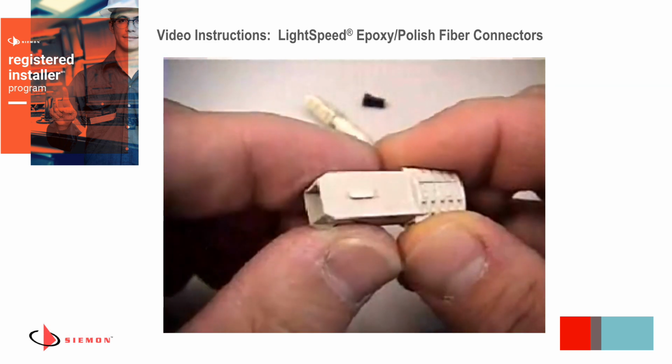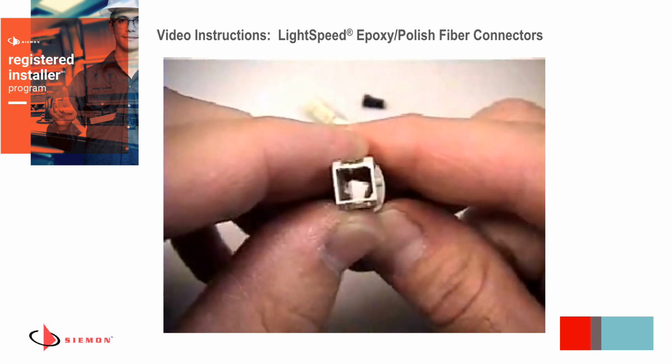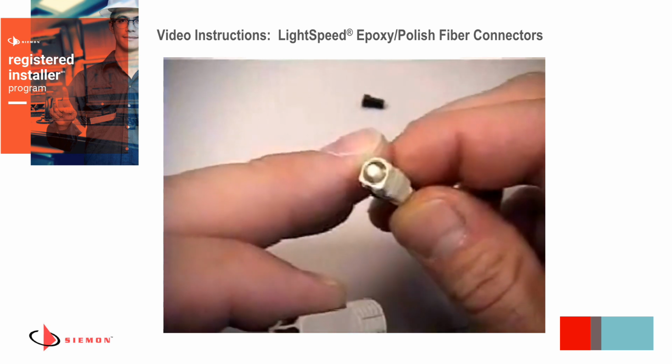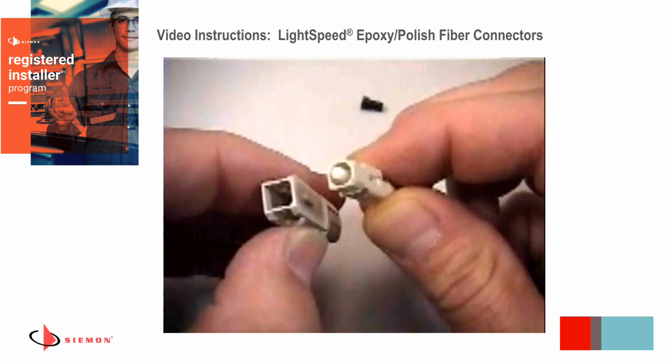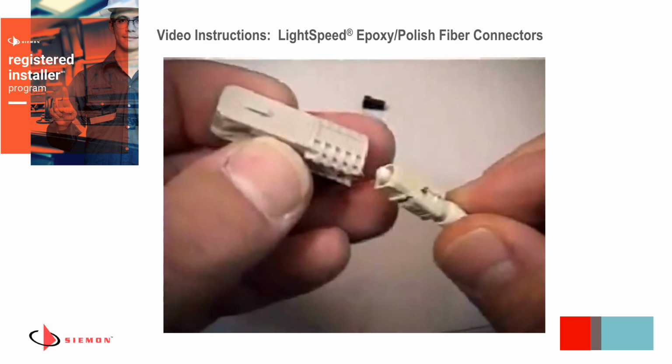SC duplex connectors will require one additional step, the housing and duplexing clip assembly. Insert the connector body into the housing by orienting the chamfered corners of the connector relative to the key on the housing as shown here. Grasp the boot and push firmly. The connector should snap into the housing.